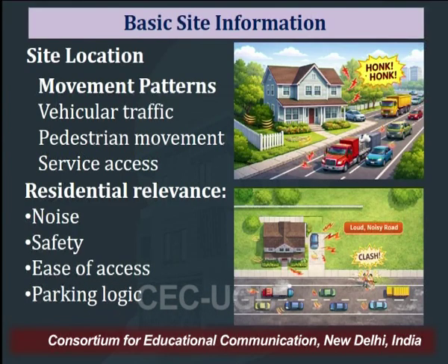Next important thing to understand is what are the movement patterns that are happening around the site, because movement patterns are basically vehicular traffic movement, pedestrian traffic movement, and service accesses. Vehicular means all the buses, cars, trucks, all these come under vehicular traffic, and pedestrian movement means it is the walkability aspect that is to be evaluated.